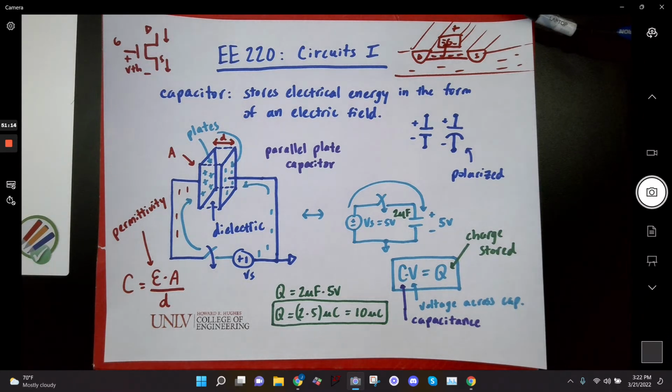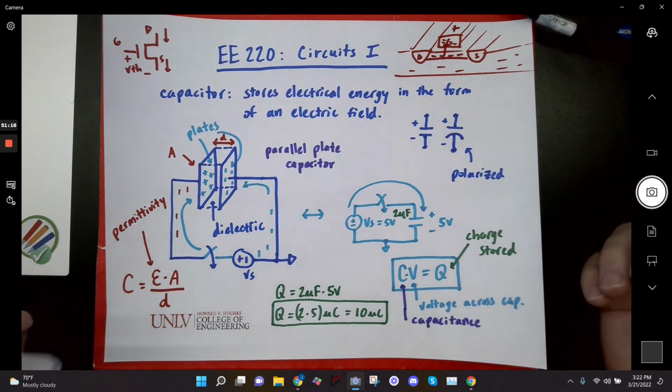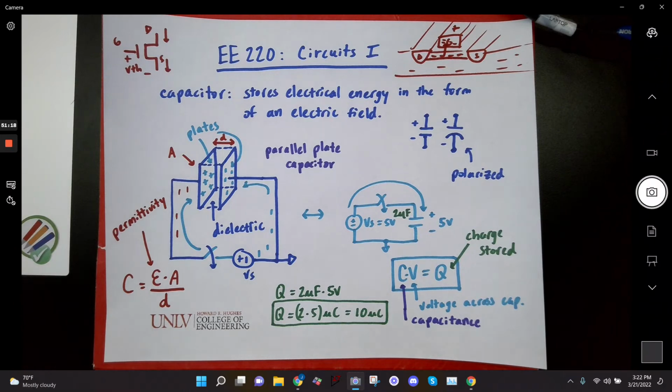Well, the data is read. Capacitors are used to read if the capacitor is charged to some particular voltage. We will measure that voltage, and then we can note. It's much more complicated, right? DRAM is much more complicated than that. There's a way that we read whether or not that capacitor was charged or discharged, and we're going to talk about that next time. Actually, one of your homeworks talks about it. It's called charge sharing.